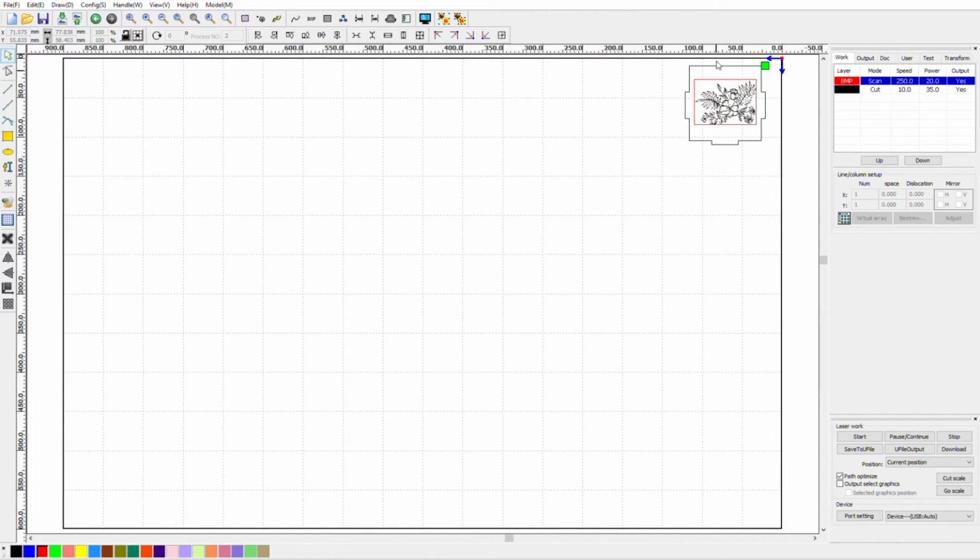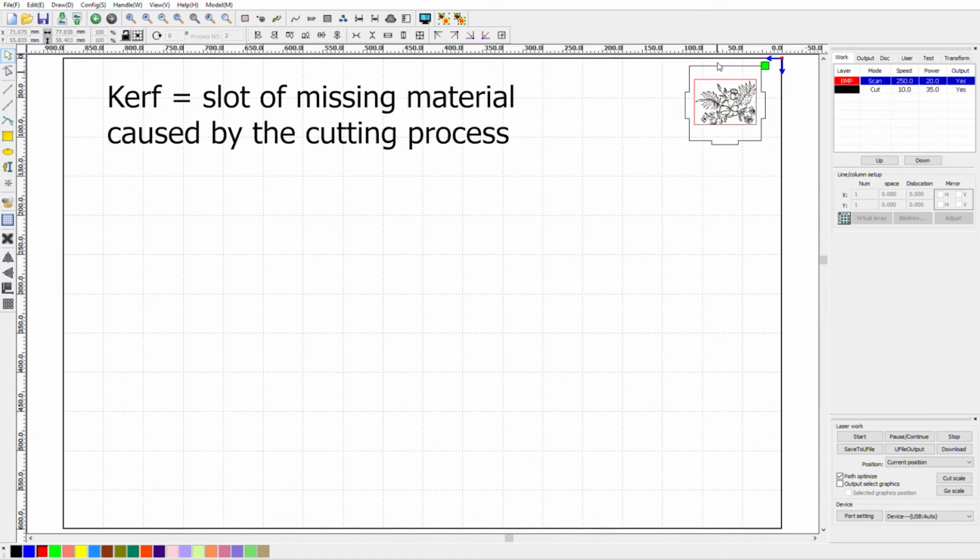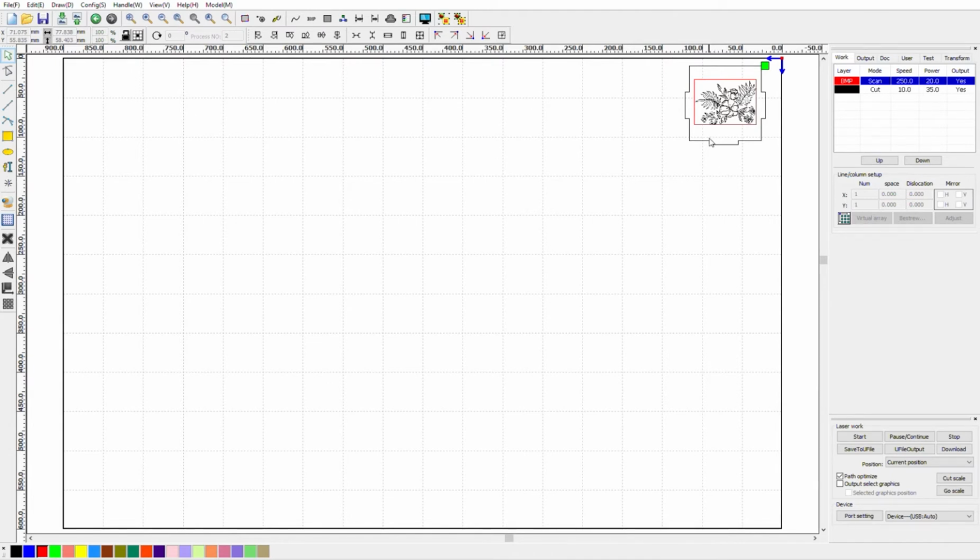They can either shake around in the gaps created by the kerf. If very small, the parts may fall through the grating into the trap below. If very light, they may get blown out of position by the blow-off air that the laser uses to keep the lens cool, keep dust from piling up, and constantly blow away embers to prevent fires. To prevent those problems, we want to keep the outer portion of a part in place while the inner parts are engraved or cut. Thus, our order of cut is always etch/engrave, inside cuts, outer perimeter cut.